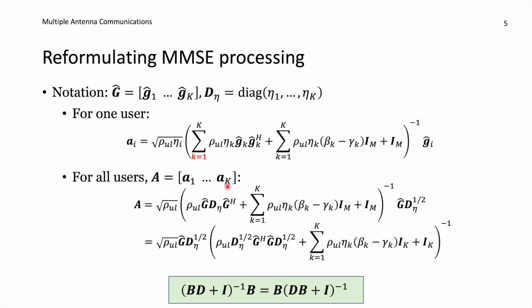that means that the channel matrix, when we take the outer product like this, is going to have rank K. And here we'll also have a rank that is K, but in this case the dimension of the matrix is also K by K. So a term like this will actually be invertible, while this matrix is not invertible. Let's now use this second expression in the rest of this video and consider the asymptotics.